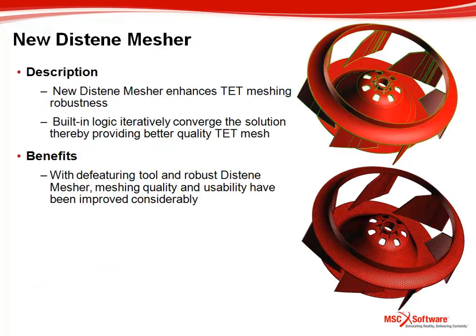The new Distene MeshGems, as I talked about before, enhances the TET meshing robustness. So here on the screen, I have a geometry that has been meshed with the new MeshGems, and you can see it's a significantly improved mesh compared to some of the previous releases.